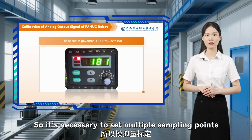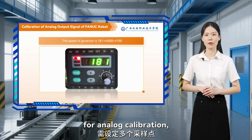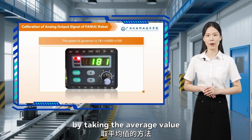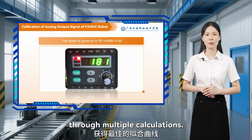So it is necessary to set multiple sampling points for analog calibration and obtain the best fitting curve by taking the average values through multiple calculations.